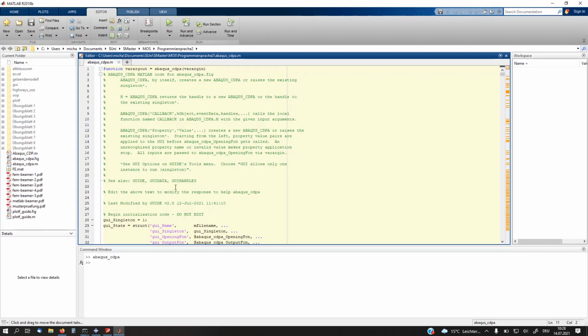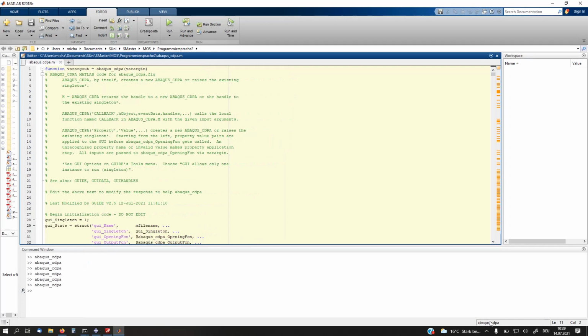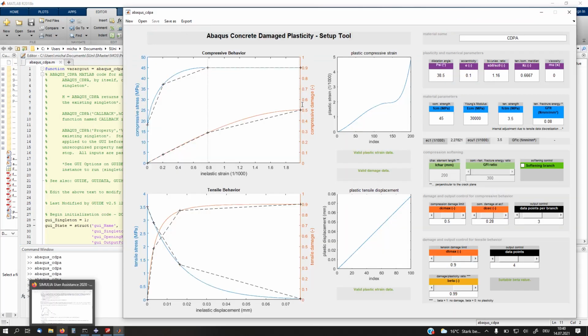So just follow the instructions in the description of this video and refer to my GitHub site to download everything you need. You're going to need the .m file and the .fig file. Make sure you copy these two files in the same folder and run the m file in Matlab 2018b or newer. I'm not quite sure about older versions, but I can guarantee that it works with versions 2018b or newer. So once you open the m file, just push the run button up here, and this window should appear. You're going to see 4 windows.